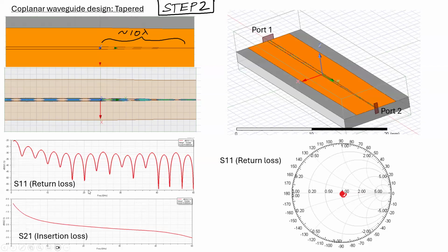I guess when they reflected, some of the frequencies got constructively interfered, some are destructively interfered. Yes, exactly. Nice. So these bumps correspond to when these frequencies, and the corresponding wavelengths, are multiples of this length, right? When the wavelength is some integral multiple of the length of this trace, you're going to get either constructive or destructive interference, depending on which one it is. So you have nodes and antinodes essentially.